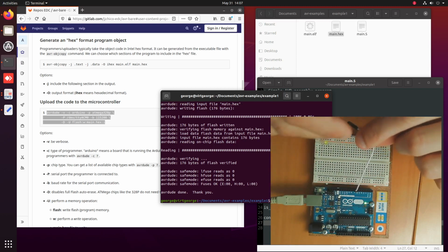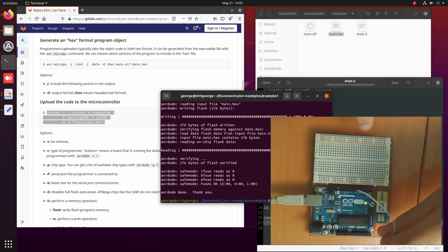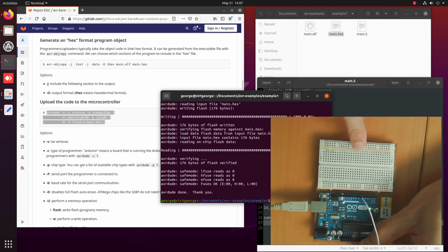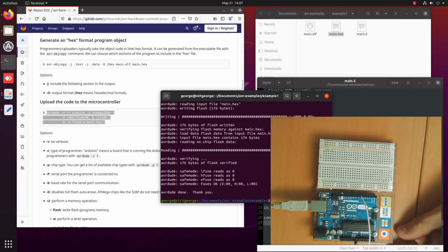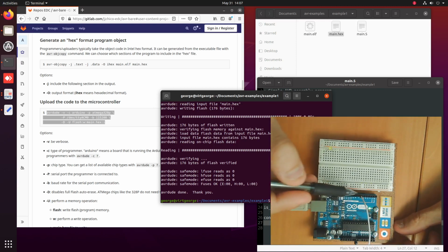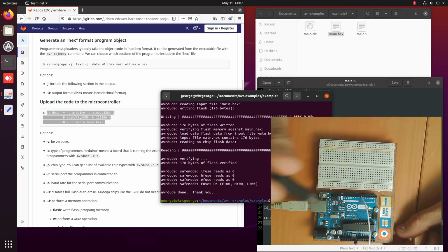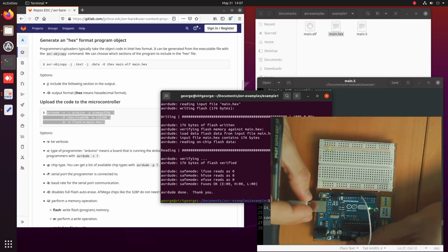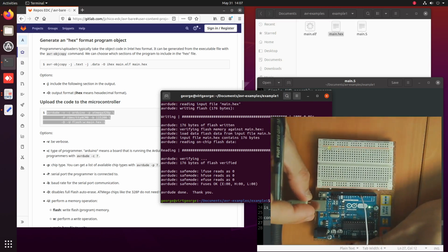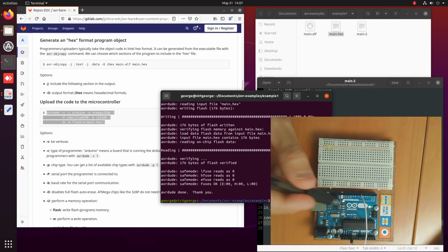Now when I connect it to 0, I can use the ground pin here. It works. We have a 0 here, and then it reads this 0 and sets pin number 13 here to 0. The LED turns off. If I change it to 5 volts, which we can take from here, then the LED is connected.